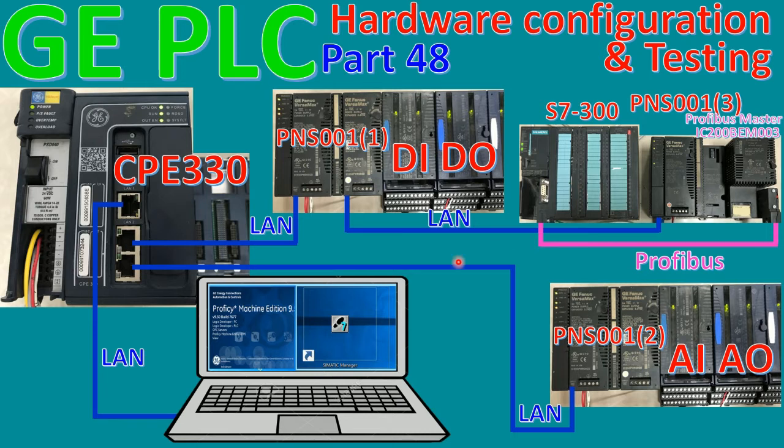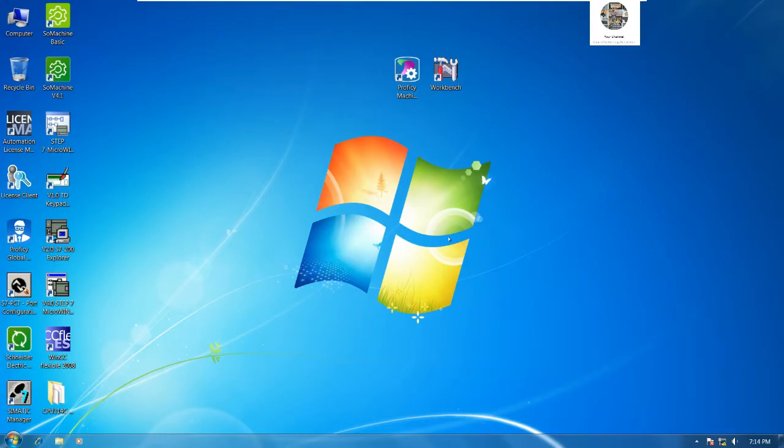Okay, so let's go. First we will configure the Profinet for this I/O and this I/O, and second we will create one more Profinet I/O and then connect the Profibus Master to the Profibus Slave of PLC S7-300. Okay, so let's go. First open Proficy Machine Edition.